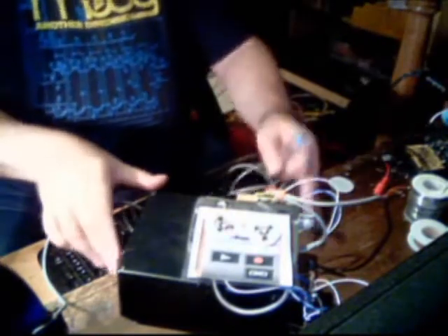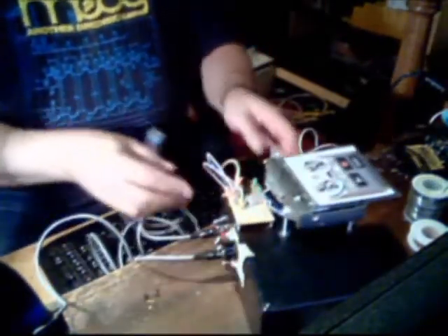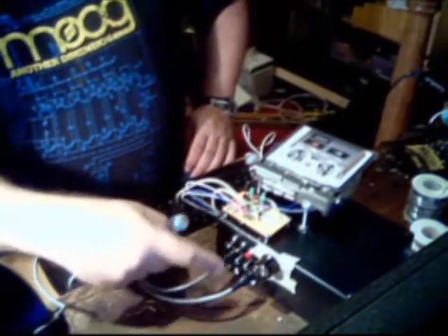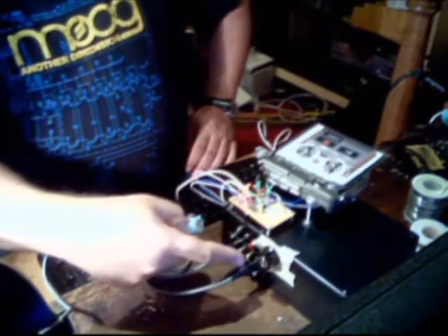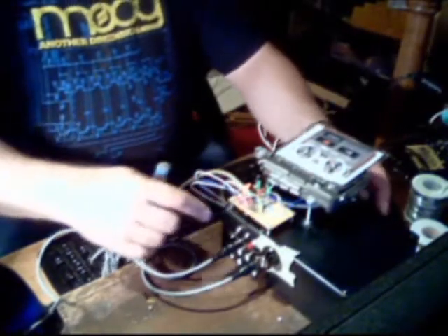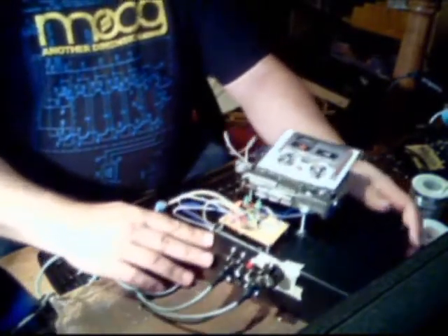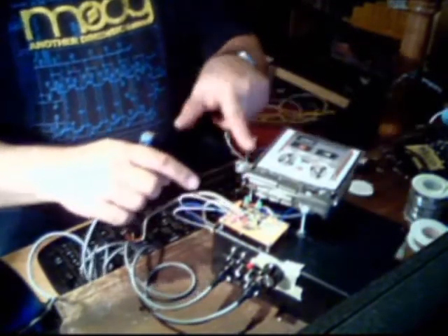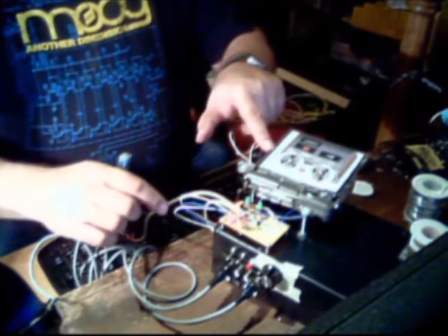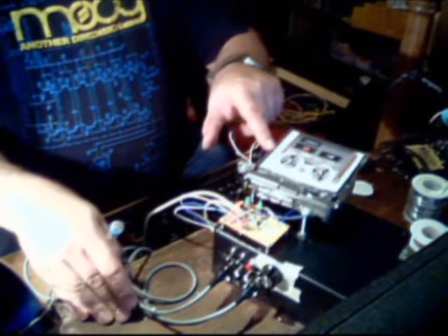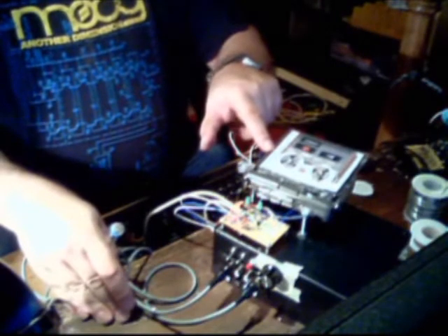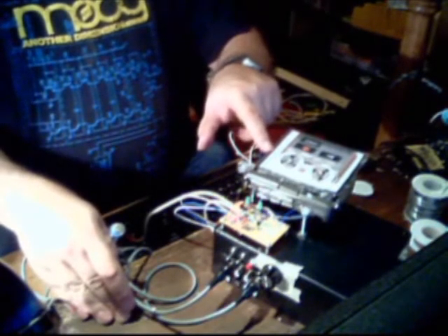On the back of the unit from your perspective, I have the inputs for the microphone, or I can do a line input, and this is the headphone, the speaker output. On the top here is a relay control board which has two transistors, a couple of LEDs, and a relay here, and there's a relay underneath the tape deck. The tape deck relay is shorting out a diode that's in series with the motor. When the relay is energized, the diode drops 0.3 volts or so and makes the motor run about half speed.